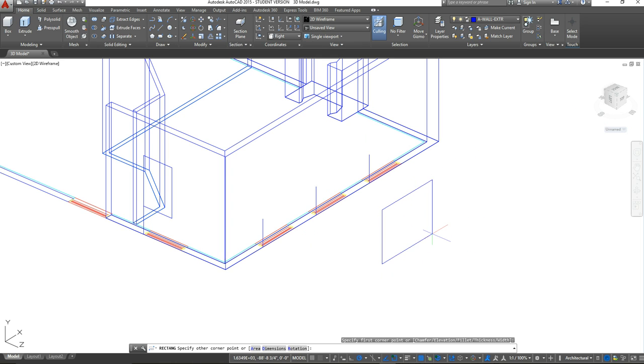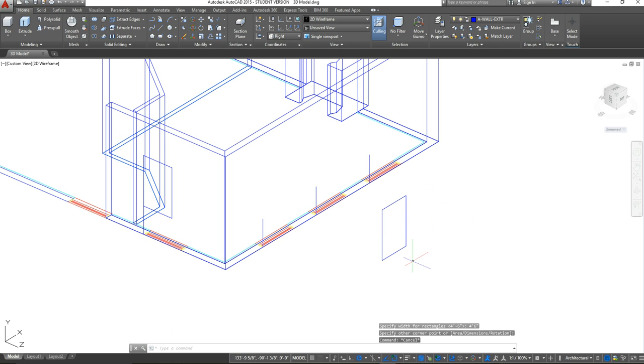Okay. So I'm going to click once to anchor that tool, and in this case, because I know my dimensions, I'm just going to go down to my ribbon here and select dimensions. It's going to ask again for the length, and you just want to do 3 feet across, which will be that horizontal dimension first. 3 feet, press enter on your keyboard. Then it's going to ask for the width, which is actually that vertical length. So I'm going to type in again that 4 feet 6 inches and press enter. Okay. And once I have that dimension, I have to click again in my model space to anchor that rectangle in my model space.